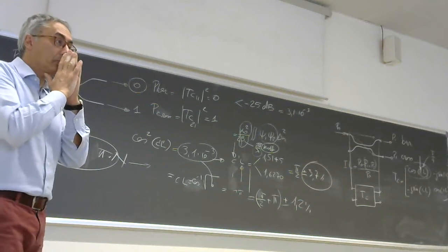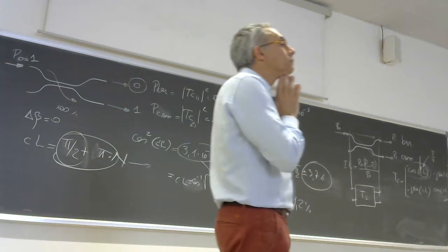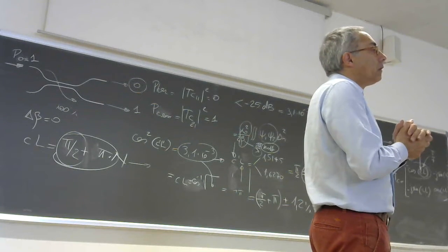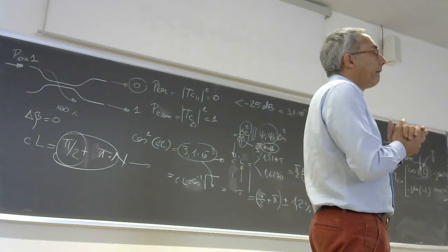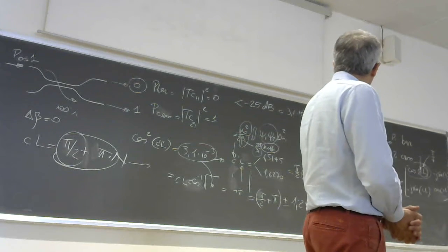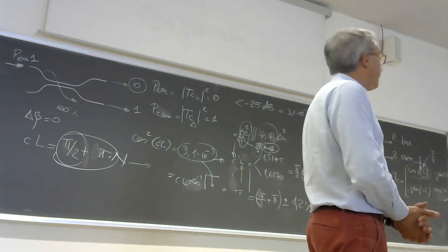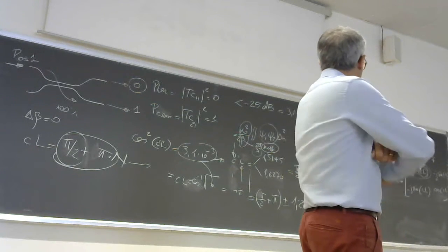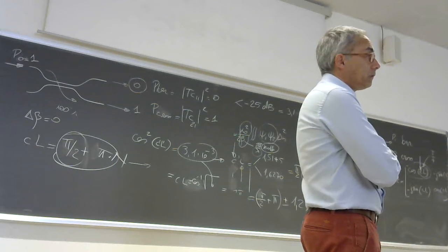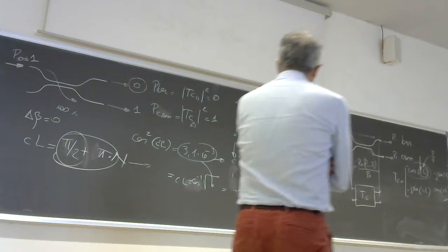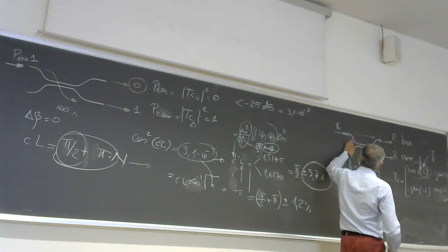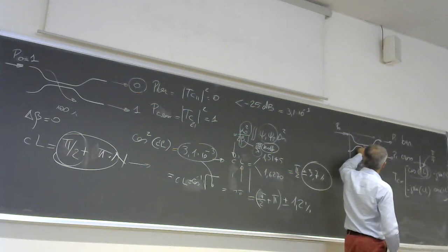Also, a longer waveguide has more loss than a shorter one, right? This is another reason for this in a microwave system: when the transmission line increases, we lose a lot of power. So this is another reason to make the device shorter, even if this device can be tens of hundreds of microns long. And most of the loss comes from the transition region, not really from this part.